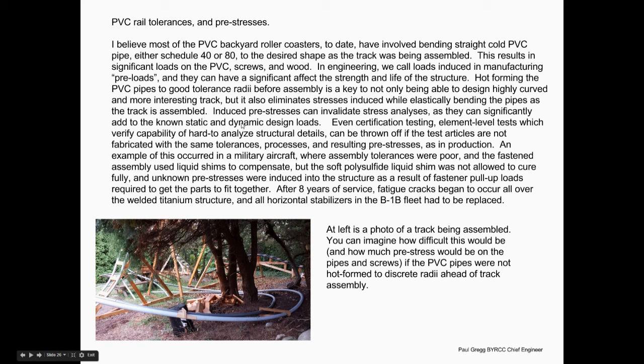This talks about pre-stresses. I won't go through the whole discussion, but basically, if you didn't pre-bend the tracks, you'd be cranking these pipes around and screwing them down as you bent them, maybe with 2 people, and that would leave a lot of what engineers call pre-stresses on the fasteners. That means they've already got stress on them before the cart comes along, and so that would add to the stress. And in sunlight, maybe this PVC, if it's bent around a bunch of frames, what we call creeps into position. In other words, the stress is reduced in time at temperature. I don't know about that, but it's always a good idea, and much easier, to hot form these pipes ahead of time with hot sand, which seemed to work really well. And that's covered in another video.